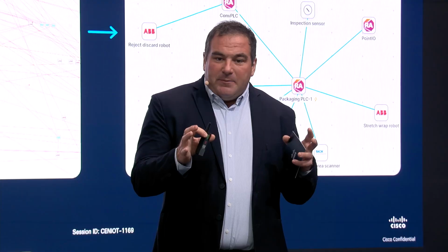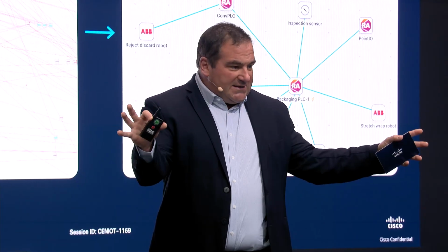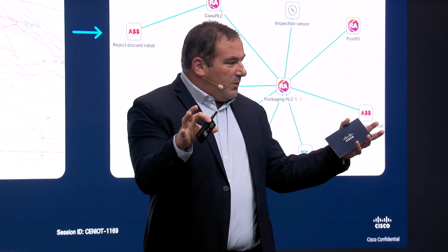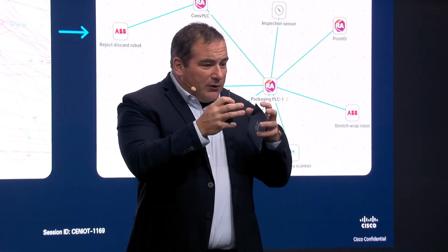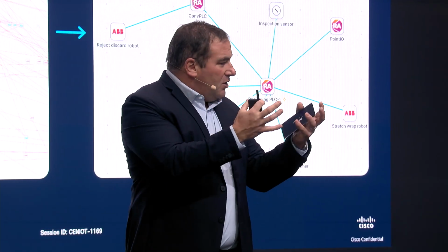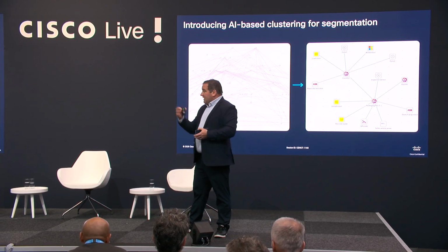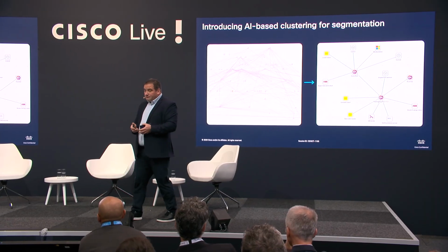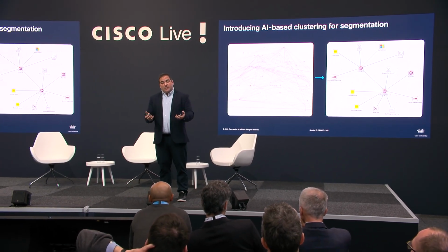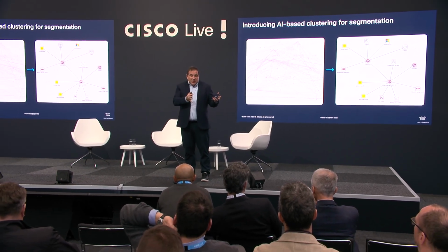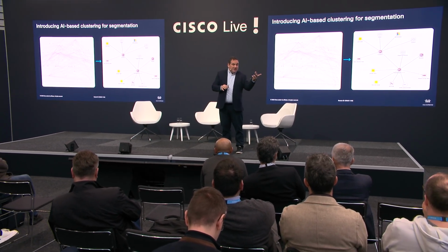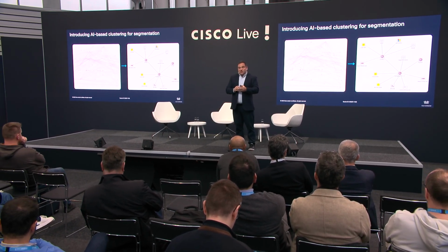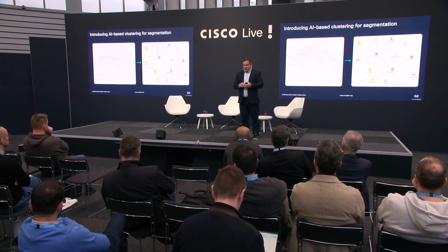And what we have done and launched last year is the ability to take all the assets that you have discovered, the communication pattern, and guide you to show you who is talking to who, and really help you to have a representation of your industrial environment. And based on that, we can start to implement some segmentation policy. Now that you see what you have, you can see, hey, this PLC should not be talking with this other PLC or things like that. So that's what we have done.